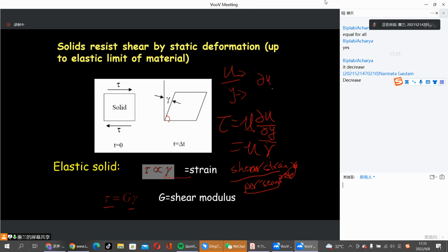And again, in your material mechanics, U is displacement. For solid, U is displacement. Do you know the difference? So we have du dy, but here U is a velocity. For solid, U is displacement. So velocity is displacement per second, right? Yeah, it's very important.